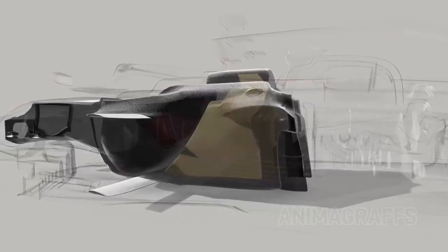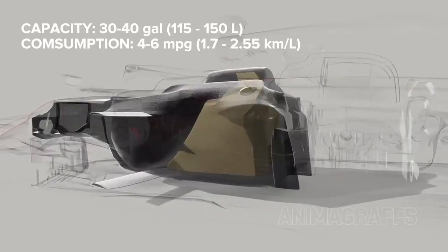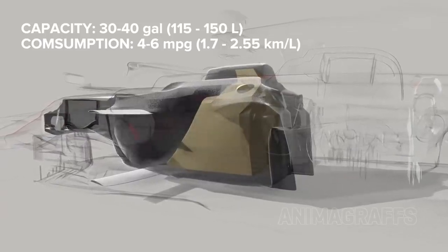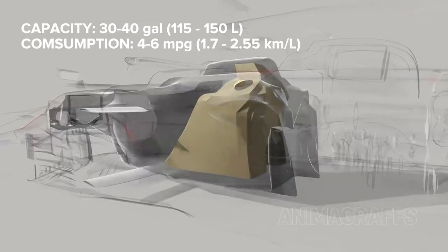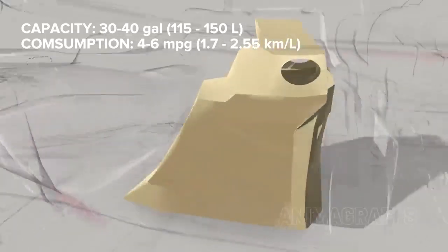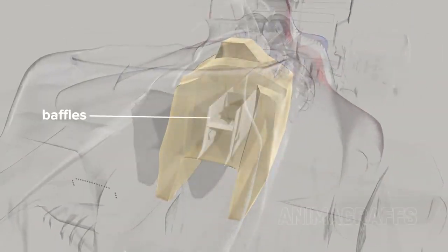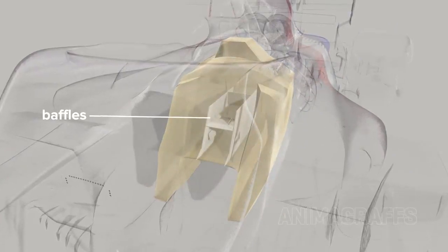F1 fuel cells can hold an incredible 30 to 40 gallons of fuel, which is just enough for a single race, as pit stop refueling is not allowed. These cars get an estimated 4 to 6 miles per gallon of fuel. The tank has various internal baffles with one-way valves to tame the sloshing liquid under incredible racing forces.